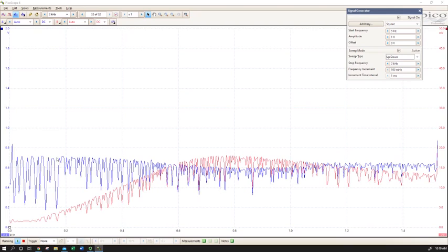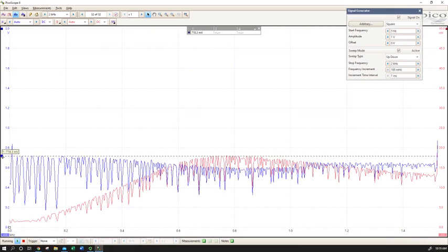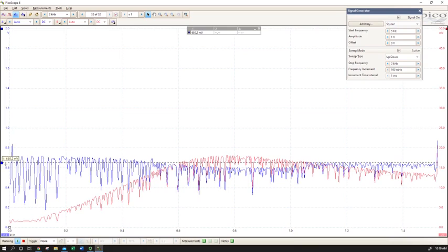And it's a little bit harder to see the trough, but it's much easier to see the peak in the resistor, but we can also see a corresponding decrease. If we look at the tops of the blue signal and we kind of draw an imaginary line across the top, we can see that it decreases from something around 700 millivolts over at the DC side down to maybe 600, right underneath where that peak for the voltage signal over the resistor is, and then it goes back up to 650 as we get out to higher frequencies where the inductor would be limiting current and therefore limiting voltage drop over the resistor.